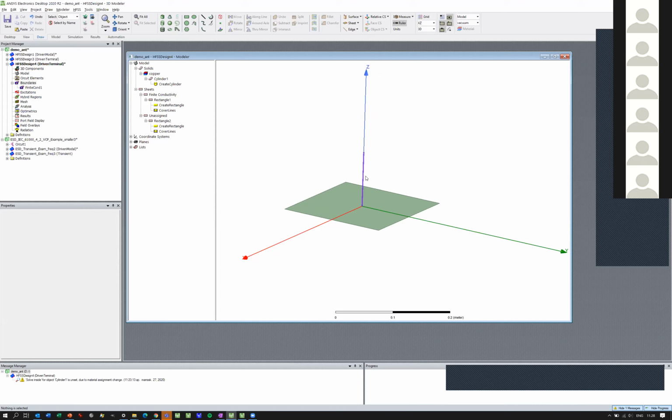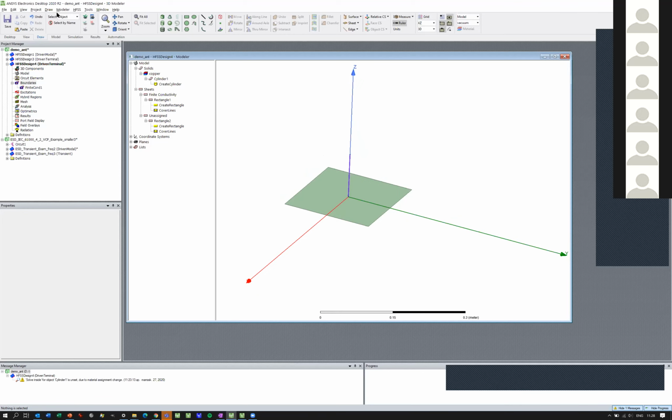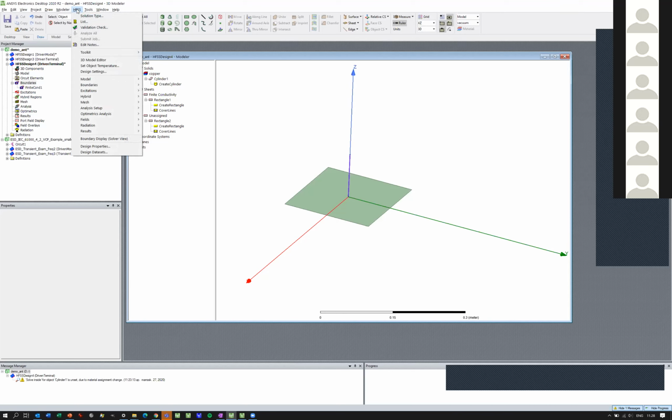Now we have to think about how simulations are behaving. So if I need to measure how this antenna radiates, I should capture all the electromagnetic waves which are kind of transmitted, radiated away. And I need to measure that. And how to measure that, I can do it with a boundary condition, once again. And typically, you need to define the boundary condition around your system, except if it's a coaxial cable, which is kind of all the electromagnetic waves travel inside, or kind of a transmission line.